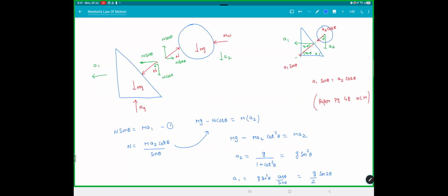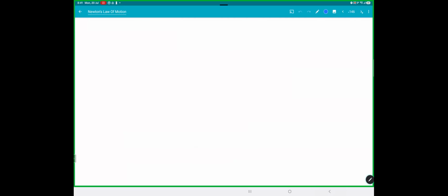But please say where it went wrong. The free body diagram, the constraint equations, resolving forces, components and solving. The process is still the same. Let them give any problem. This is the process. Something changes, you know the way to do the adjustments. All clear with this? Yeah. Next time.